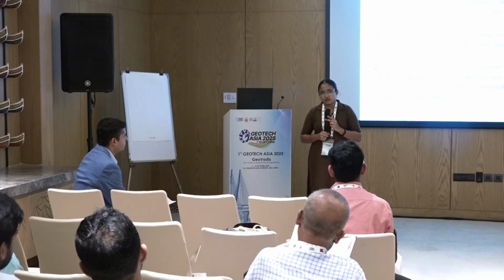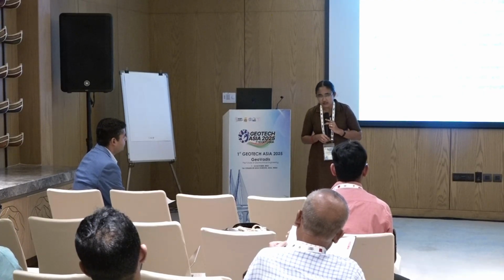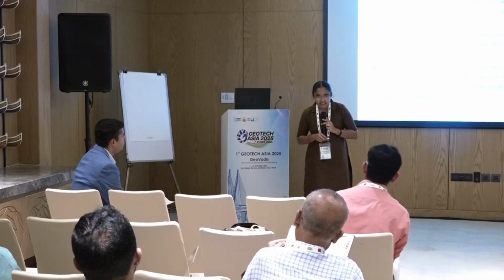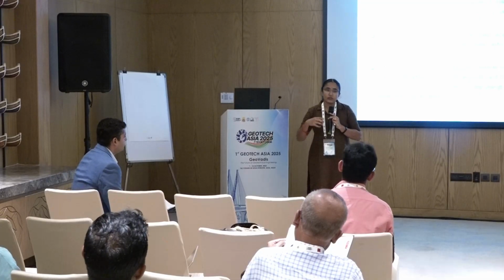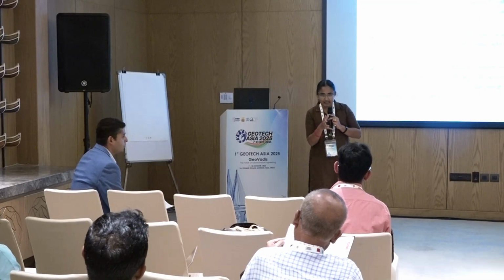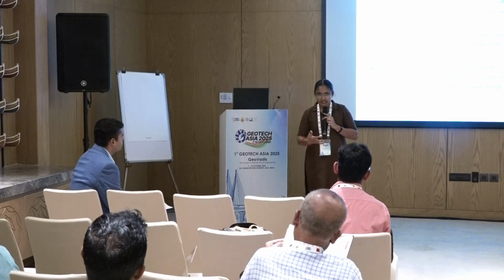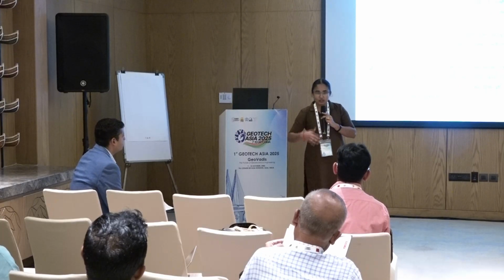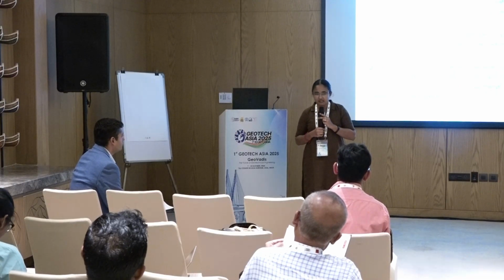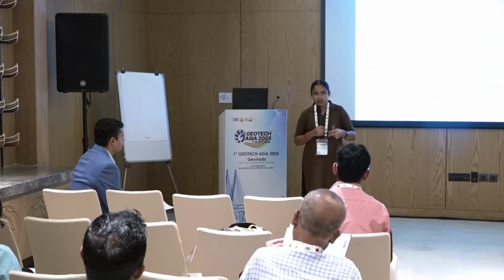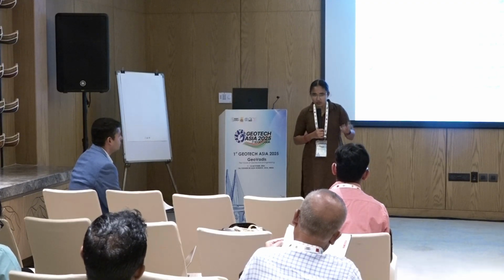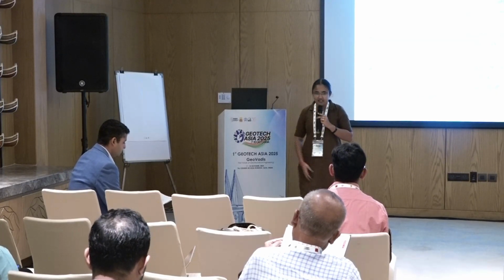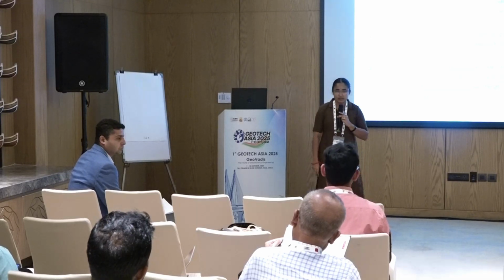Apart from this, you said xanthan gum is a good option, but we are having the problem of degradation. Yes, until it is fully saturated. When it gets saturated, the binding action crumbles instantly. So if we make sure the soil does not reach that critical saturated condition, if it stays in a compacted condition, say in a semi-arid region where rainfall is not frequent, it may not go through that wetting cycle continuously. In that case, it would be better.